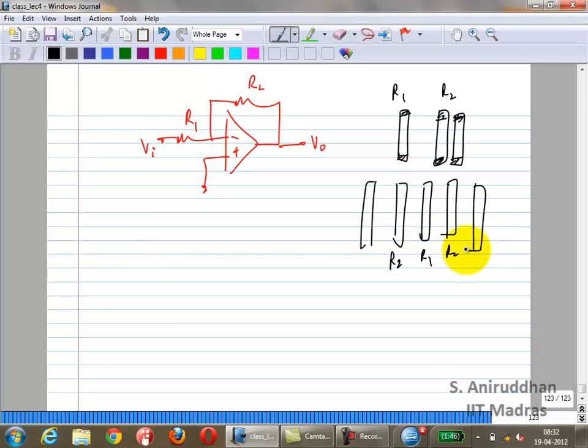No, you can place them apart, right? You can place them wide enough apart such that you don't have a lot of capacitance, but close enough such that the gradients are good, right? So the idea is you are trying to make the environment around. So R1 has two resistors on either side. You want to make R2 also the same way. Correct? Okay.